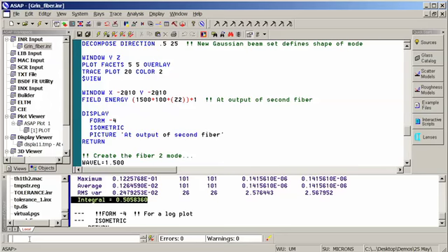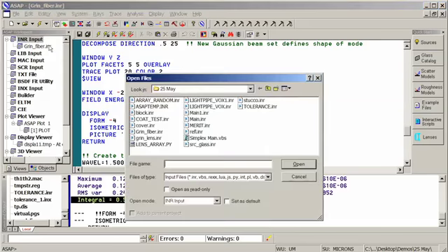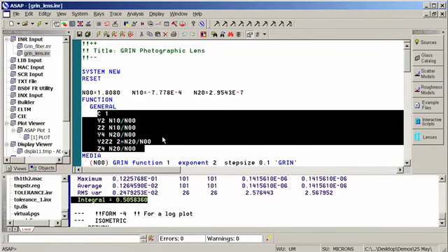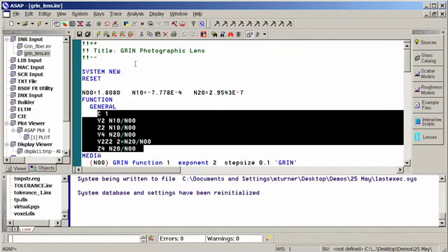In addition to optical fibers, many optical systems have lenses made of gradient index materials, and these are a more large-scale version of gradient index. Obviously, the GRIN fibers tend to be much smaller in diameter. But we also have gradient index lenses, and to define a gradient index material, you'll simply need to define the manufacturer's parameters that describe the properties of that optical material and define a media that then uses those properties. And to propagate through, let's take a look at the results.